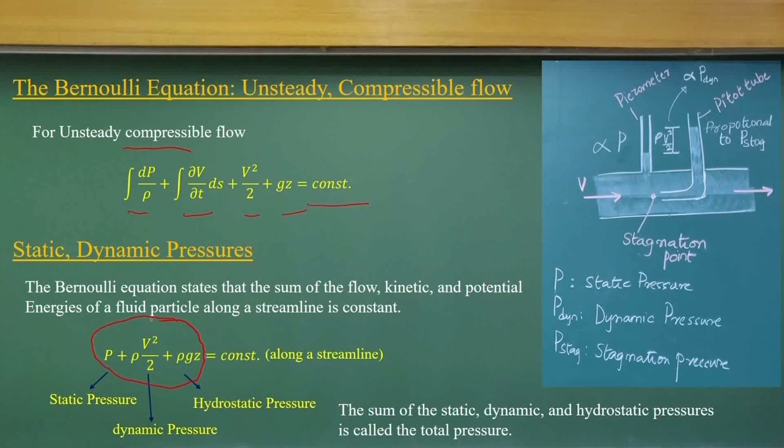As I discussed earlier, this is the summation of three energies. Flow energy, which is because of the pressure at that location: how much work is done by that pressure is the flow energy. You have a velocity field, which has kinetic energy, and fluid particles, or virtual fluid balls, staying at a particular height from a datum, which gives potential energy.